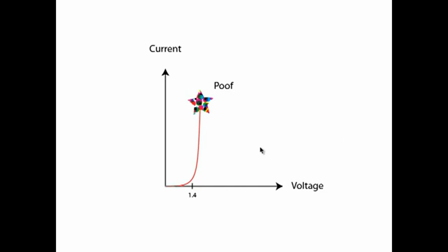The simulation for the LED in EDISON is not as realistic as a simulation for the bulb. It will allow you to abuse the LED quite a bit before it goes up in smoke. So be aware of this when you're working with real circuits. We want to avoid the poof factor. So put the resistor in series with your LED.